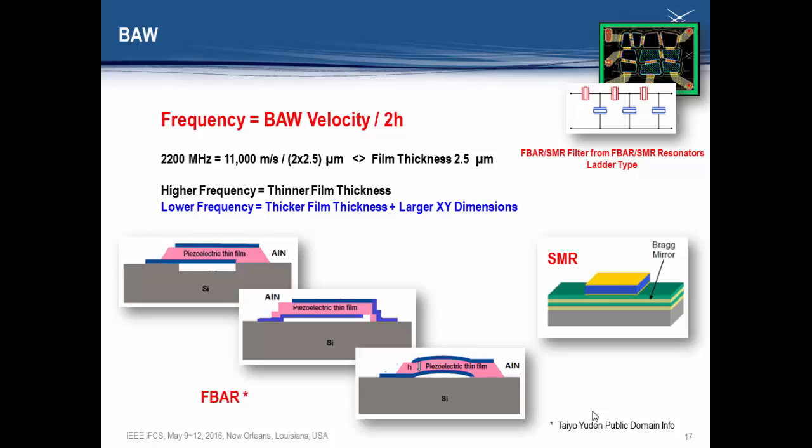There's another technology, SMR, which they call a solidly mounted resonator. It's a little bit like FBAR, except that they don't have an air cavity. They just use Bragg reflectors, layers of different materials, to reflect the wave back and create a resonance. So I have two here: one is FBAR, the other SMR.